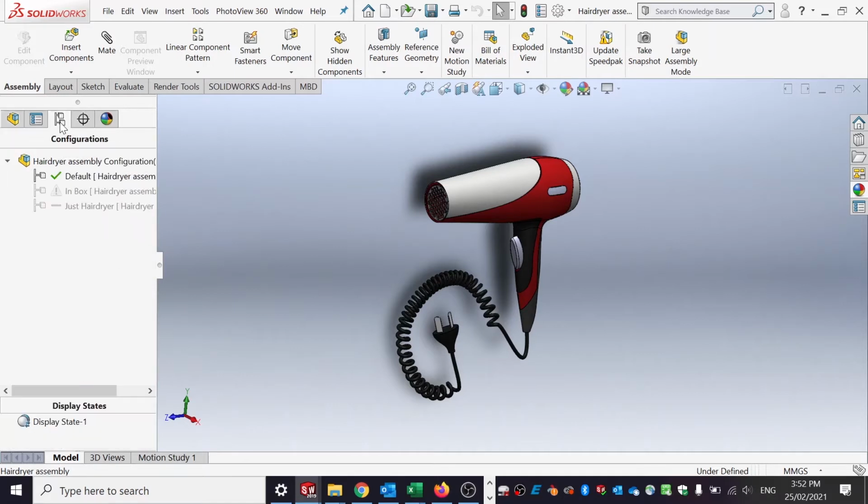So to start off with, I'm going to show you how to create an exploded view. Now we go to the Configurations Manager. If you haven't used configurations in the past, I highly recommend that you look into this some more. Configurations are extremely powerful. You can create configurations of individual components. So with different configurations of, say, different colors, one configuration might have certain features turned on or off, perhaps a hole that's in one but not in another. And the possibilities for creating different configurations for components is almost endless. You can have different dimensions for different components in different configurations as well, so it's very powerful.